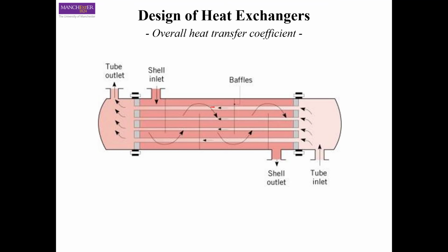So all these lines, actually the light color lines, they are tubes, okay? So it means that the tubes are fixed in these two headers, and the liquid that is coming through this header goes through the tube, passes all the way, and comes out here. At the end you have the sum of all the liquids that are coming from the tubes, and then it goes out, okay?